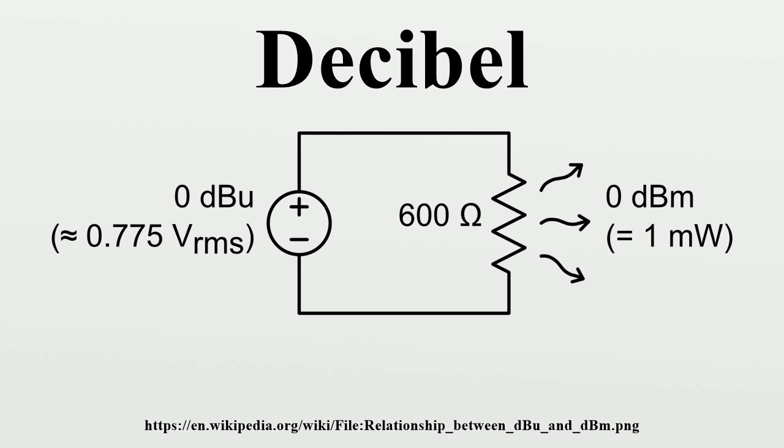Examples: all of these examples yield dimensionless answers in dB because they are relative ratios expressed in decibels. The unit dBW is often used to denote a ratio for which the reference is 1 W, and similarly dBm for a 1 mW reference point.